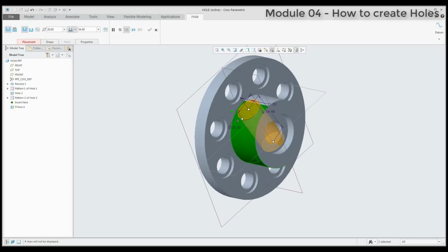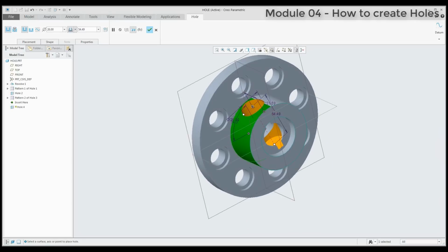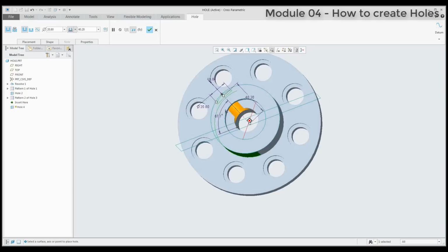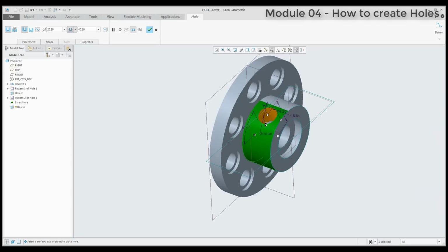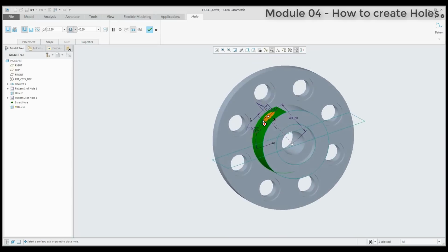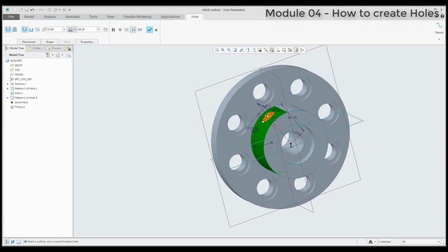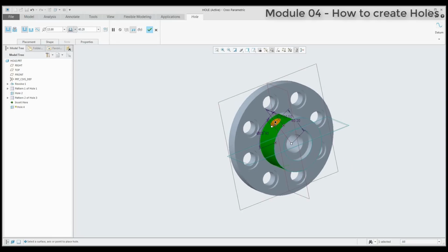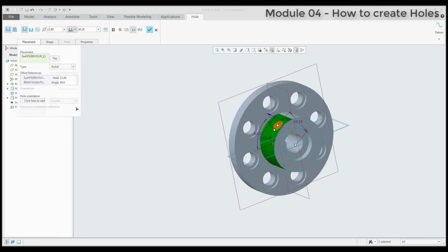So it will be good if you will specify the angle. So select the middle plane, and the system will create for you the, I will change the dimension a little bit. Yeah. And you can see the system is always oriented directly to the middle axis and offsetted by dimension. You can see all dimension here. So selected surface is this one, and offset references is surface and datum plane. So you can change the dimension here directly, and for example 45 degrees.